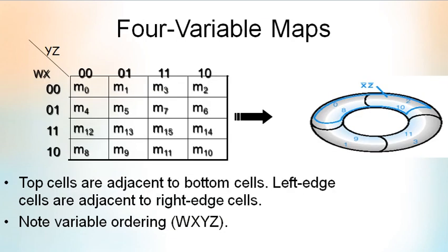When we have four variables in our Boolean expression, we have to use this four variable Kmap for simplifying the Boolean expressions. The working of this Kmap is like three variable and two variable maps. We can represent two variables row wise and two variables column wise, and the values are like for three variable maps, 0 0, 0 1, 1 1, 1 0.